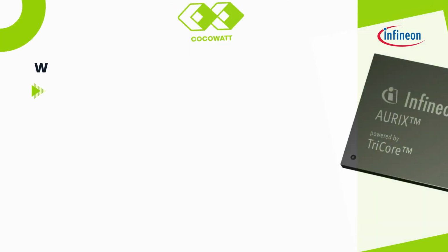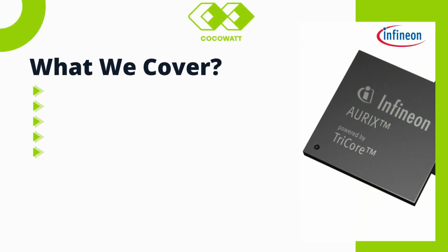So here is what we are going to cover in today's session. First we will dive deeper into the AURIX 275 GPIO architecture, building on our previous introduction to modes like push-pull and open drain, and we are going to cover what ports are available and what alternate modes are available in the AURIX microcontroller. Then we will jump into our first demo, configuring a GPIO to blink an LED, perfect for understanding the output in action. We will then go through a code walkthrough of how to initialize pins, set modes and control output programmatically.